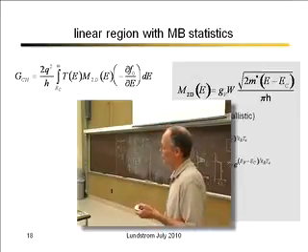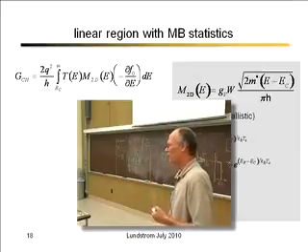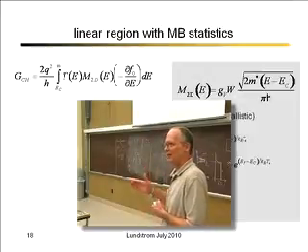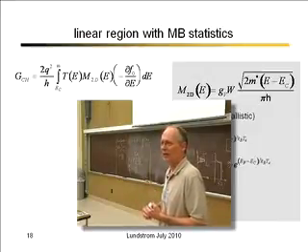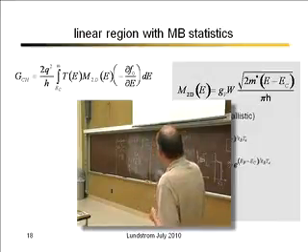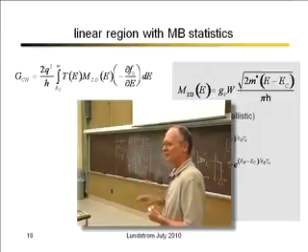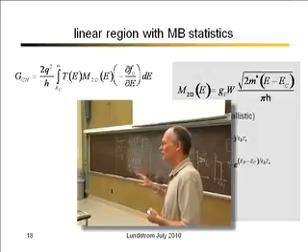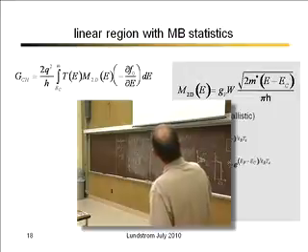It's a good approximation in sub-threshold, but I'm only going to talk about above threshold. Above threshold, the device operates somewhere between this limit and the complete degeneracy limit, and that brings in more complicated mathematics, Fermi-Dirac integrals and things. A lot of textbook MOS theory is worked out with Maxwell-Boltzmann statistics. So one of the reasons I'm going to do this is that it allows us to connect with common expressions we see in textbooks and see what's different. So I'm going to do it with Maxwell-Boltzmann statistics.